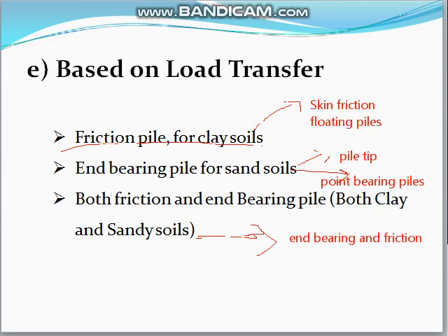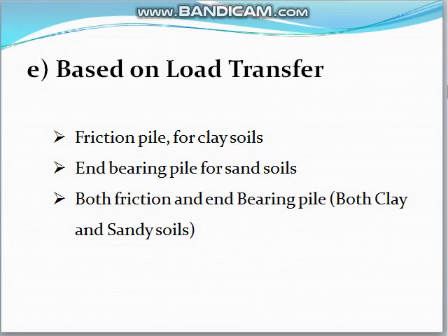Next, last one is the combined end bearing and friction piles. Here, load is transferred by the combination of end bearing at the bottom and friction along the surface of a pile. So this is all about the types of piles based on load transfer. Okay, next slide.